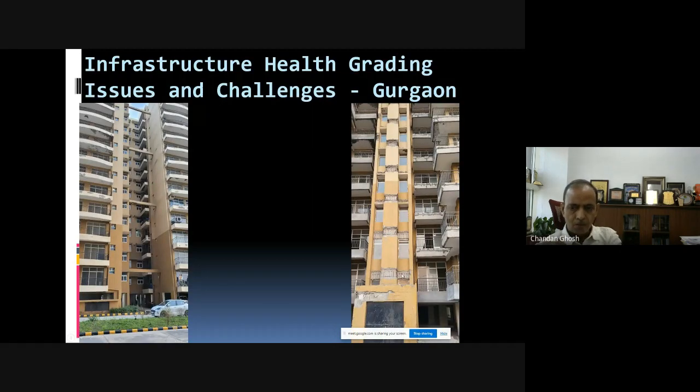If this is the kind of repairing, then who says that these buildings are unfit? If these are filled up with micro concrete or something after scratching them out, all these joints, and it becomes fit. But what is the cost then? Again, as engineers, when we have made this construction, we have to check whether there are genuine problems of structural safety or not. And if genuine problems are there, how quickly, easily and affordably these can be corrected, isn't it?